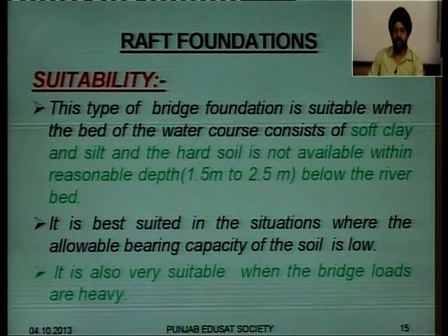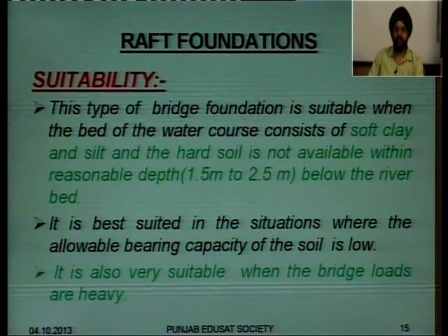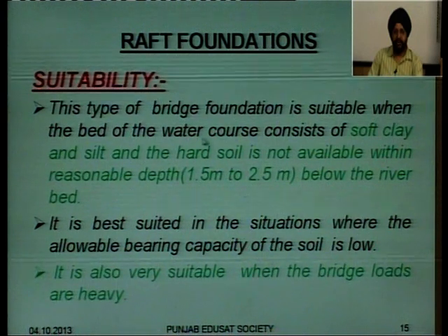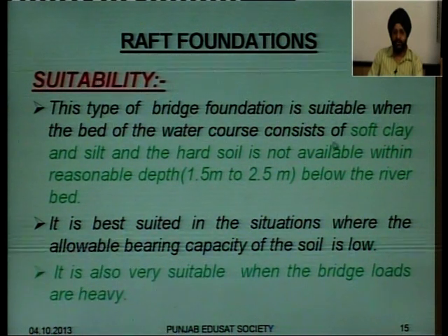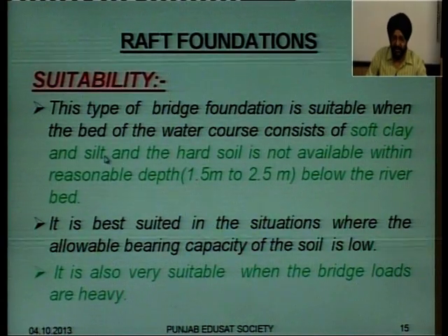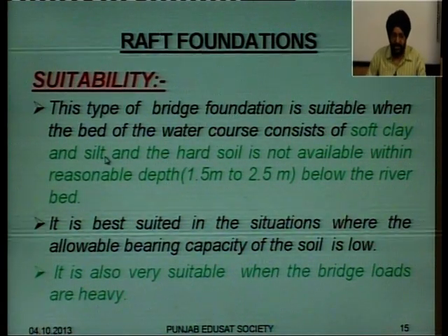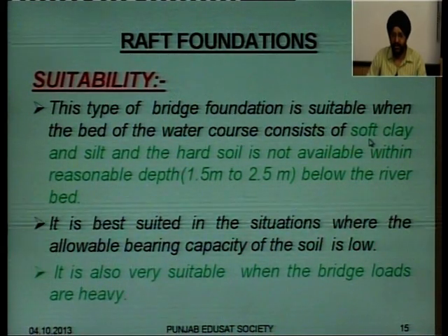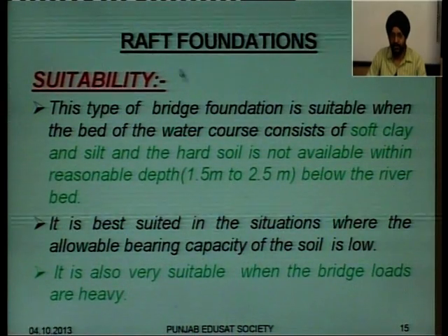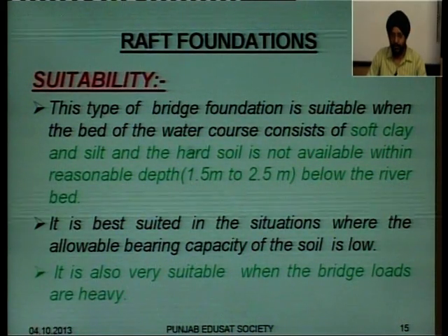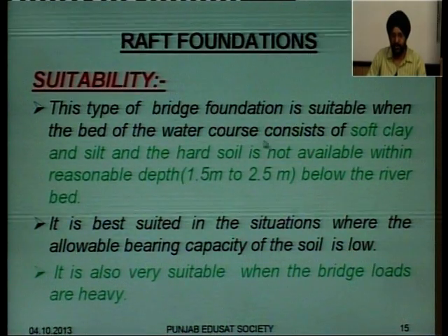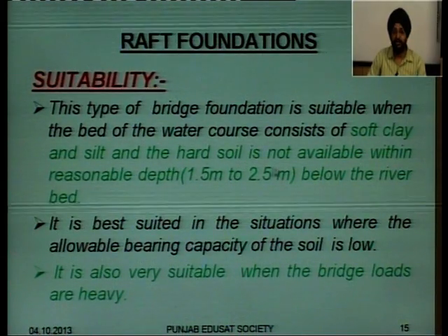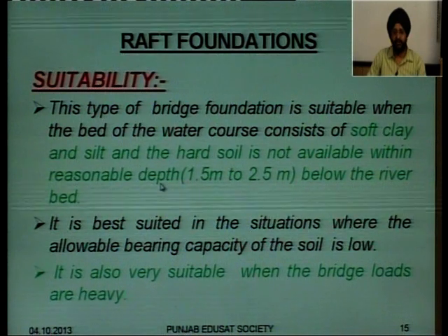Regarding its suitability, where are these raft foundations more suitable? This type of bridge foundation is suitable when the bed of the river course consists of soft clay and silt. This is how it differs from spread foundations. In the case of spread foundations, we require hard soil, but raft foundations are very much suitable where the bed of the river consists of soft clay and silt, and the hard soil is not available within a reasonable depth.